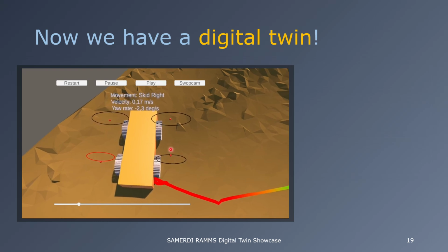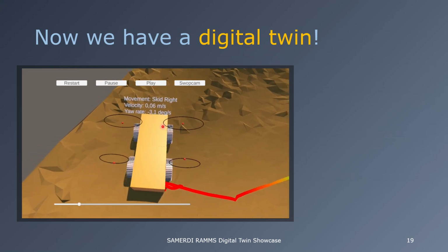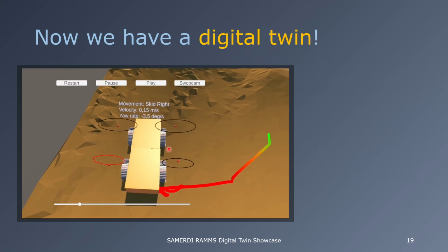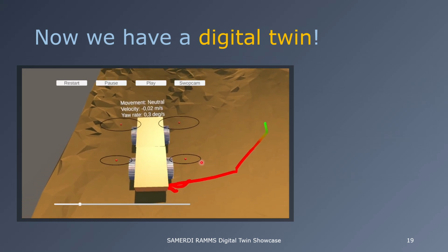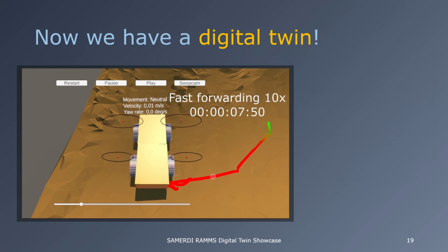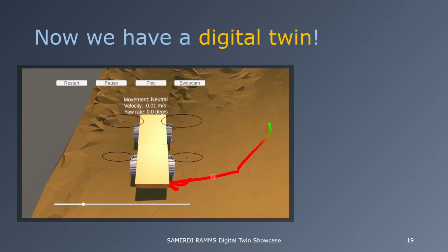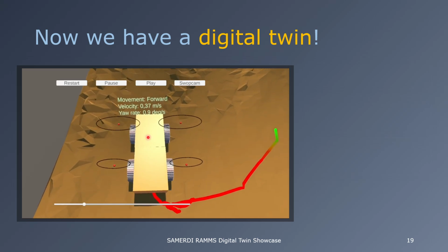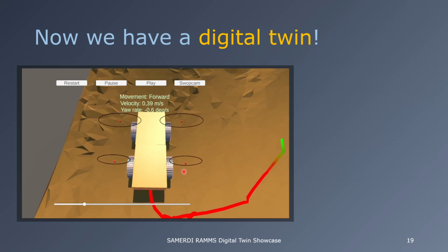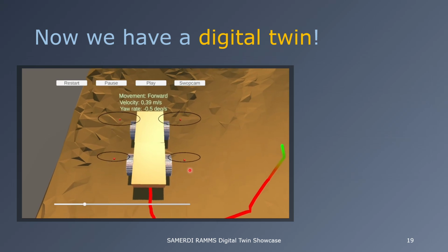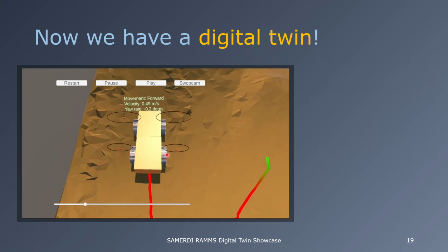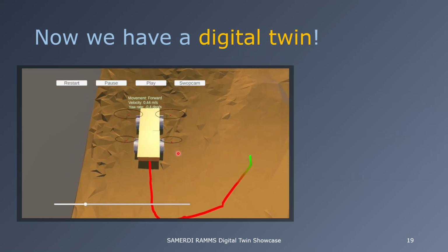And there's multiple factors that influence these envelopes. As I mentioned, it's wheel normal forces. So if this vehicle is traveling on a slope, these envelopes will naturally shrink, showing the operator that they have less traction to work with. Alternatively, the faster the vehicle moves, the further back these dots will go, for example, like right now, and the operator can see they're probably driving at a good speed now, but they probably shouldn't go much faster, or else they're at a risk of slipping.